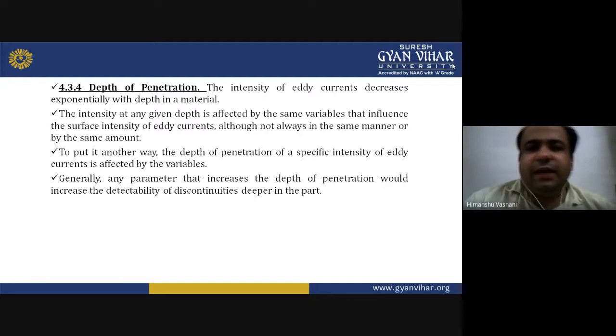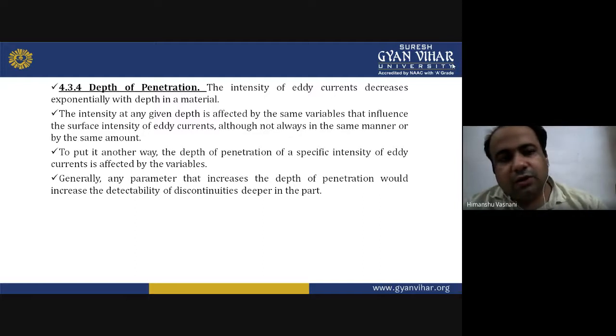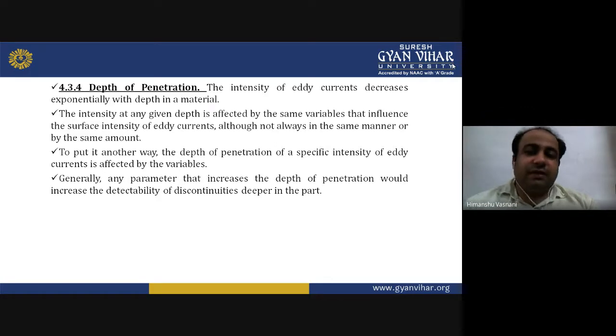The intensity of eddy currents decreases exponentially with depth in a material. The intensity at any depth is affected by the same variables that influence the surface intensity of eddy currents, although not always in the same manner or by the same amount. To put it another way, the depth of penetration of a specific intensity of eddy current is affected by the variables.